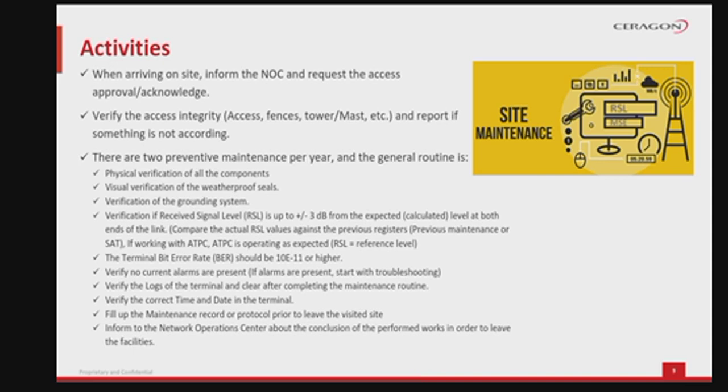There are 2 preventive maintenance visits per year, and the general routine covers the following aspects. Physical verification of all the components. Visual verification of the weatherproof seals. Verification of the grounding system.